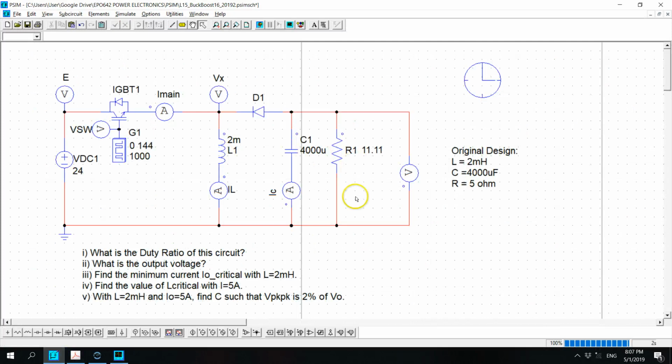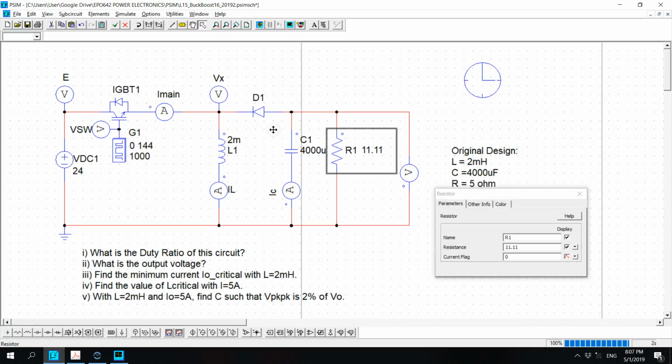Hence, having said that, if I make the output current lower than that, such as the value of R is going to be increased, for example, to 15 ohm, I'm going to increase R, therefore the current will be reduced below the 1.44 ampere.